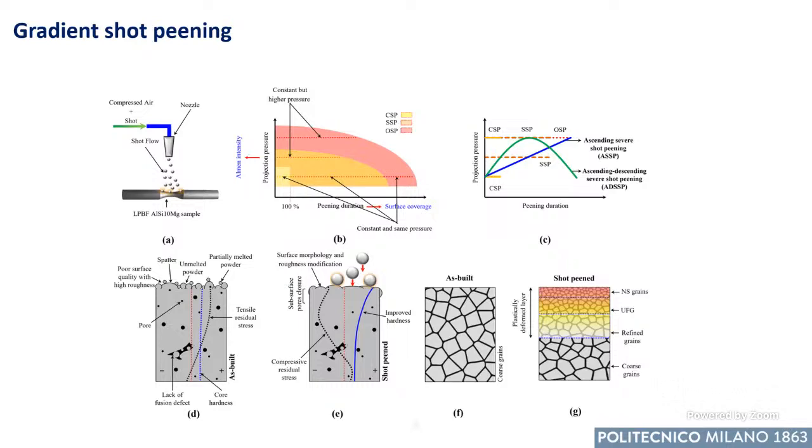And in this case, why are we doing that? Because we think that we are improving the final quality of the surface, reducing the roughness. So we don't need the electropolishing anymore to get good fatigue strength. So we avoid the problem that is related to overshot peening, where the quality of the surface in terms of roughness is quite bad, and we don't need any other treatment.